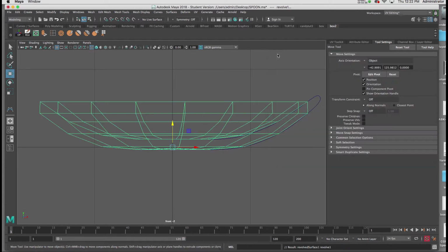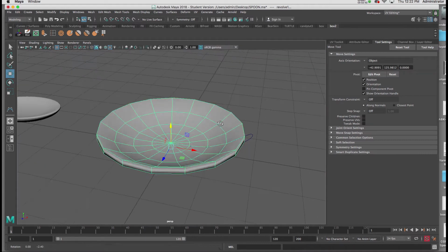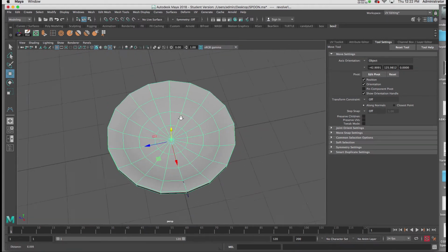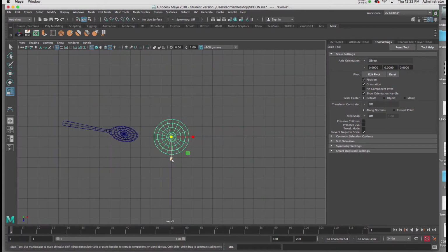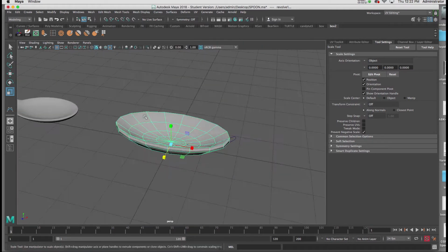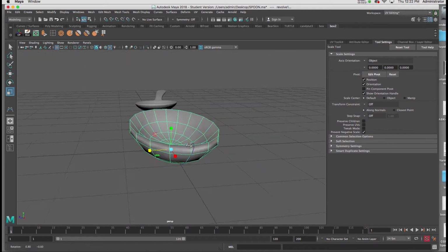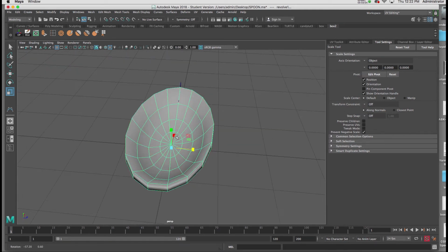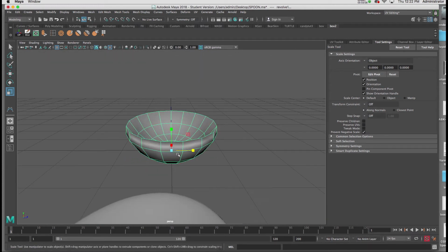And if I go to my viewport now, I've got what looks like a bowl, but when I scale it in my top view with my spoon as a reference, I can squeeze it on Z-axis, and now I've got the opening or the base of that spoon. Now I have to identify what I want to extrude this from. So I'm going to pick a face where it will allow me to make it somewhat symmetrical with the handle, which is this side here.